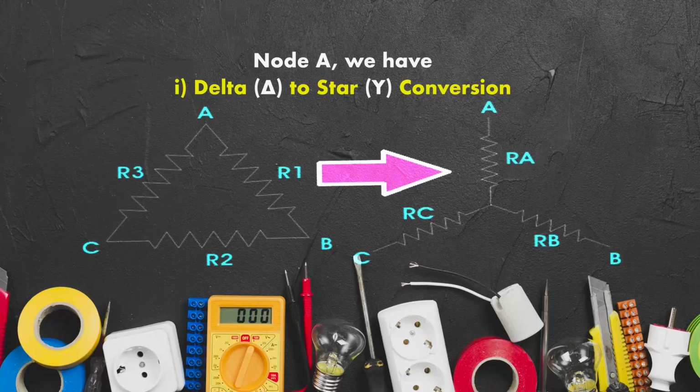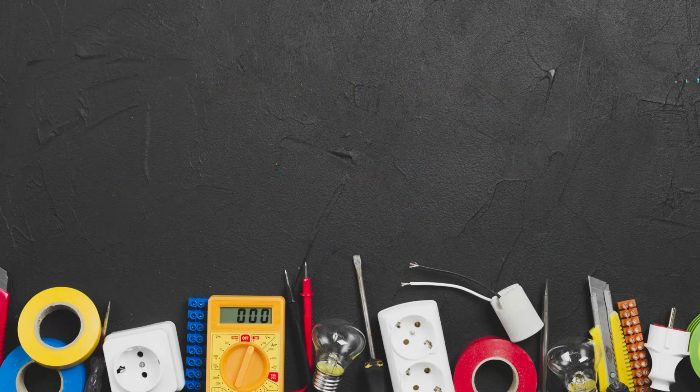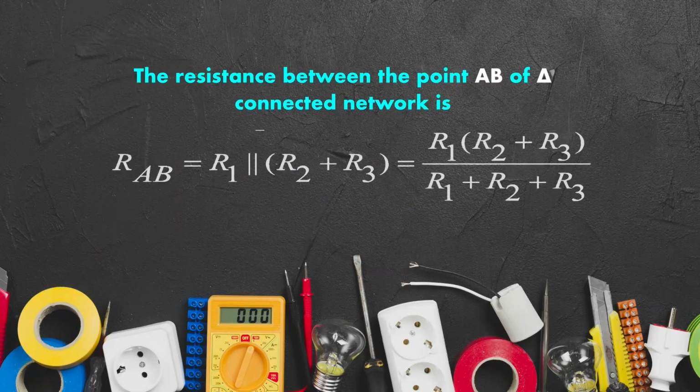So for delta and star network to be equivalent, it is necessary that resistance appearing between each of three pairs of the terminals AB, BC and AC should be the same. The resistance between point AB of delta connected network is what? RAB can be written as R1 in parallel with R2 plus R3. So it can be written as R1 multiplied by R2 plus R3 upon R1 plus R2 plus R3.